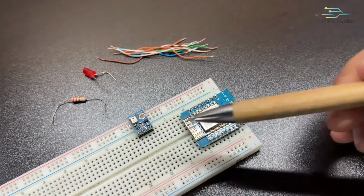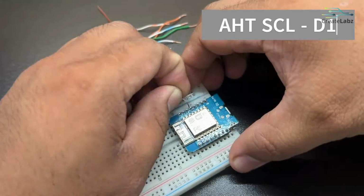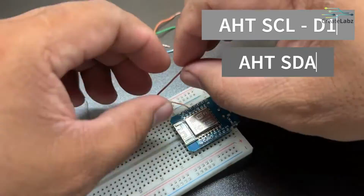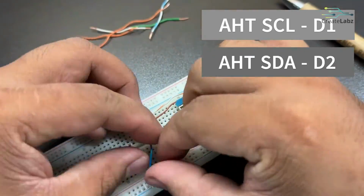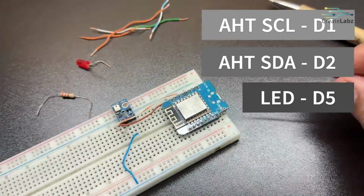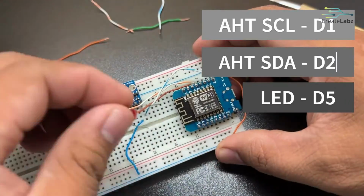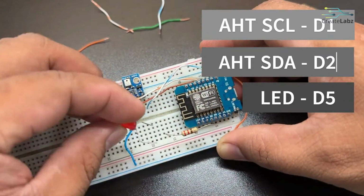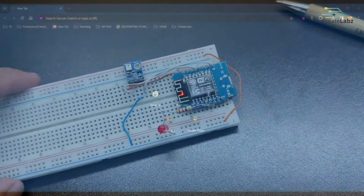Make sure that all devices are connected. The AHT sensor is connected via SCL and SDA on Wemos. These are marked D1 and D2 pins in the Wemos board. The LED is connected to GPIO14, marked D5 on the board. Do not forget the 5 volts for the AHT sensor and ground connection for all devices.